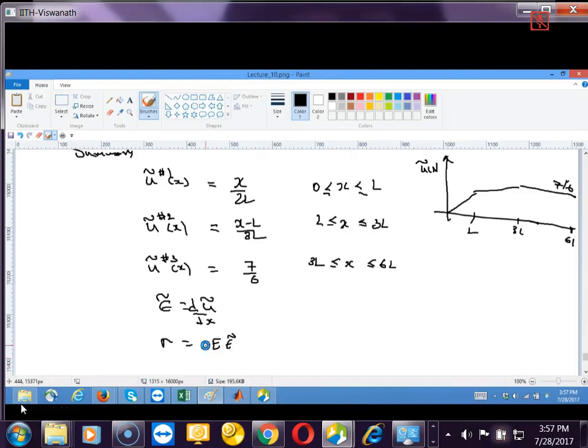With this, we'll complete today's lecture, where we looked at p convergence, and then showed how to get the stiffness matrix for a bar element. Using the stiffness matrix of a bar element, we solved a 1D problem with 3 elements, 2 nodes per element, and then we got our solution and presented it. With this class, chapter 2 is over.